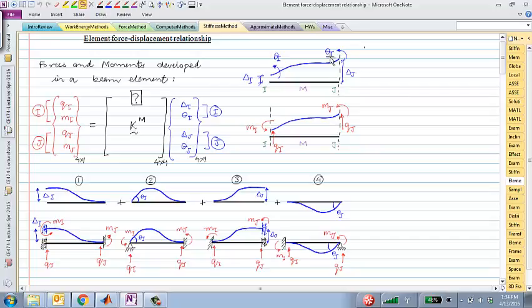The first job always in a beam problem is to discretize or divide up your beam structure into a number of elements, nodes, and so on, and then assemble what we have called the force vector, the forces and moments. This is the force vector in general, and this is the displacement degrees of freedom for a beam element.